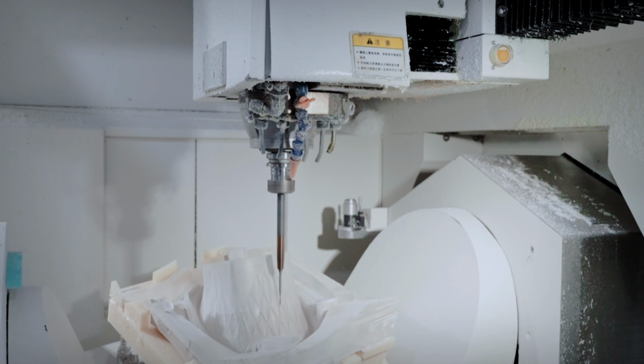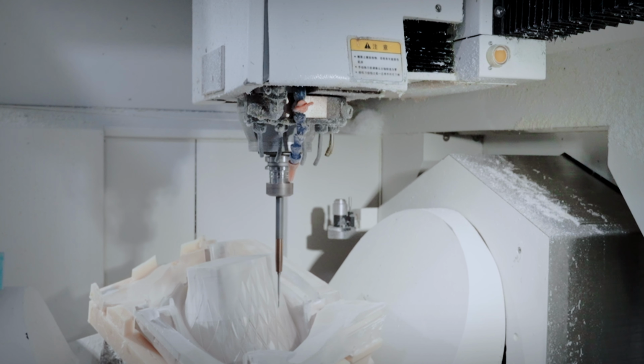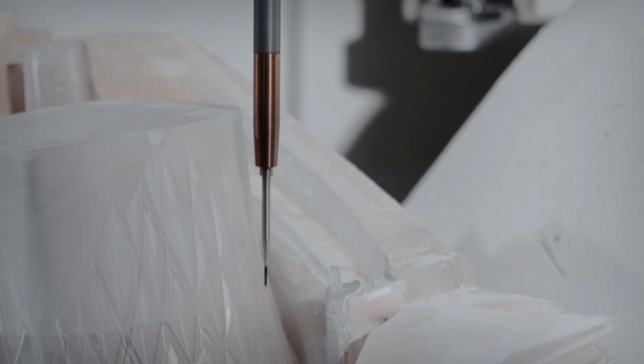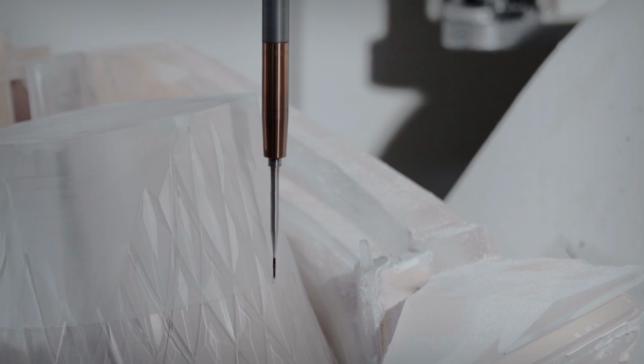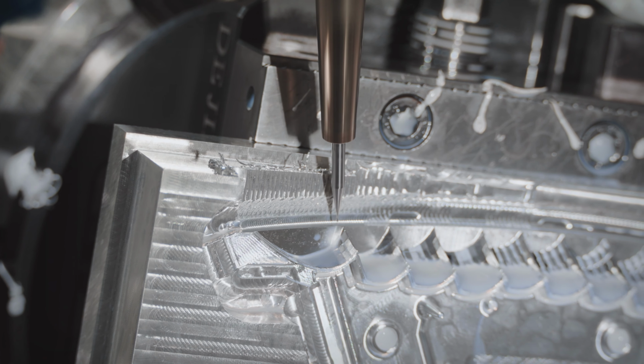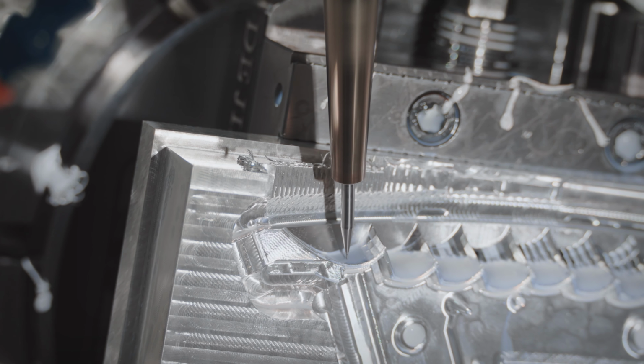The lower the surface roughness, the smoother the surface effect. But that also means using small tools and machining at a slow speed, which increases the cost. So, generally, for structural parts, unless the surface has functional requirements like installation or sealing, other surfaces and internal structures can have lower roughness requirements to help save costs.